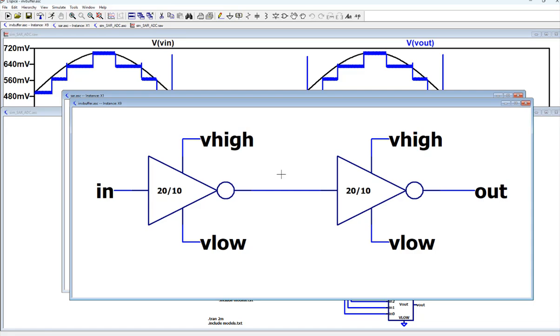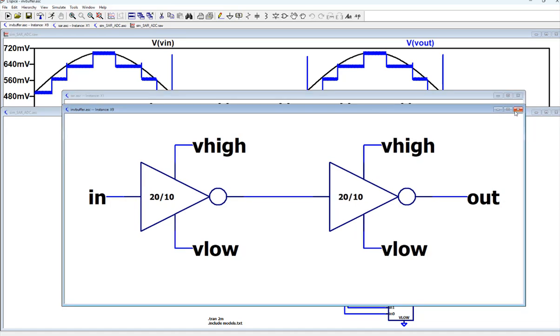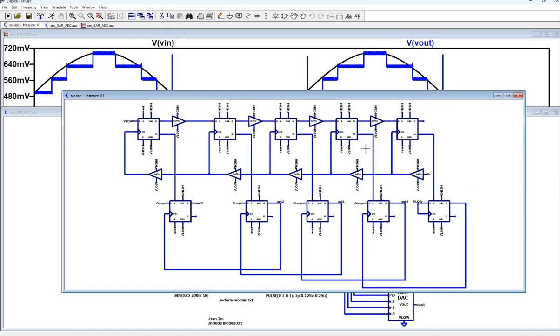It's just 2 parallel PMOS, just increasing the channel. So whenever it drives things, it has a bigger channel to dump current from VDD. It helps with having more reliable pulses. So I found out I need to use it, then just plugged it in. So these are all buffers, nothing else, right?